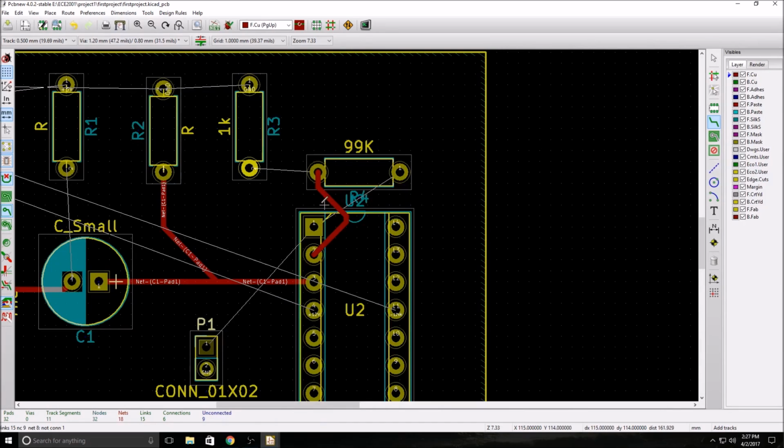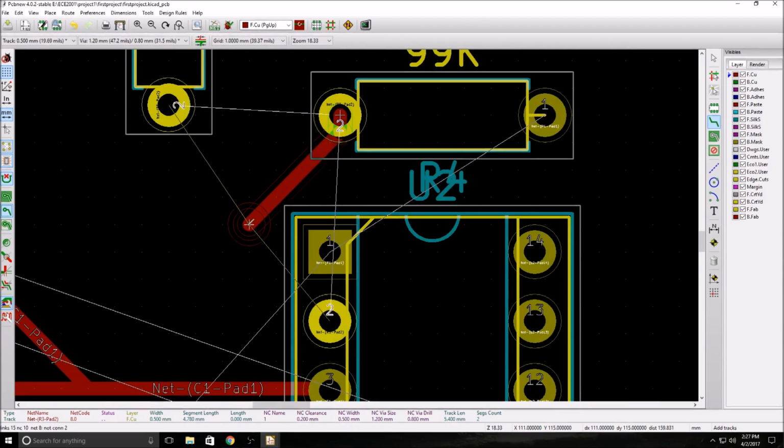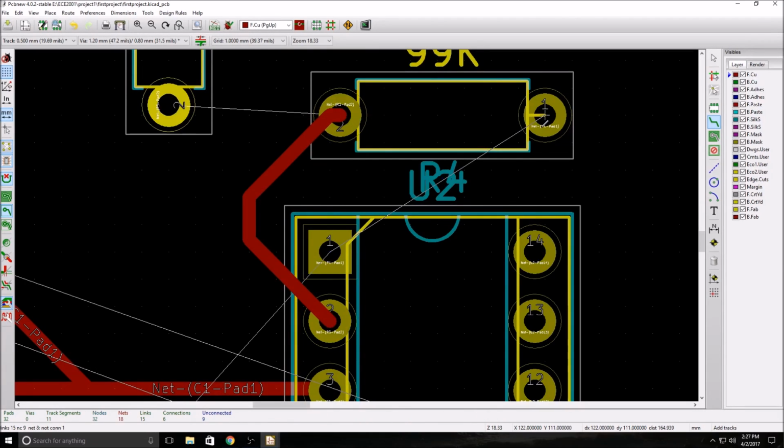Cancel. Let's try and rotate this around the other side, so this takes a lot of time. Now there is an auto route tool that you can put in the design rules that you have, and then it will go from there. But it's always better to draw your own tracks, because the tool doesn't always make the best decisions.